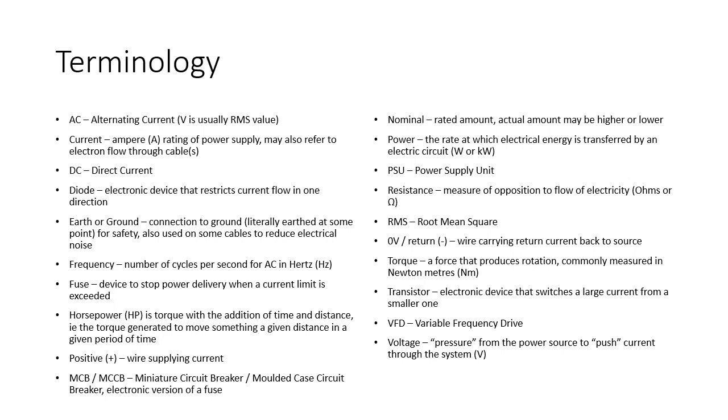This is something that has a place in VFD applications. For example, the motor cable will have some resistance, the motor windings will have some resistance, but generally the resistance should be very low. We're more concerned about reactive aspects because we're operating at AC frequencies. If you just try and measure a DC value on a wire, that's very good to test continuity, but it doesn't really tell you much about the system.